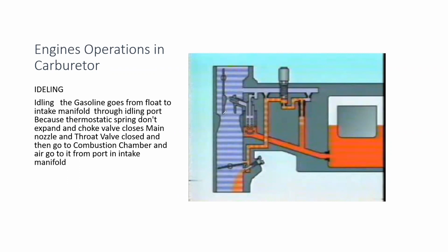So over here you have the venturi. As usual, there are two venturis. This is the secondary venturi, and this is the primary venturi. In addition to that, you have different components here. This is known as the mixture screw. Actually, a mixture rod. So there's a small component inside the carburetor which measures how much fuel is being delivered into the engine, right?